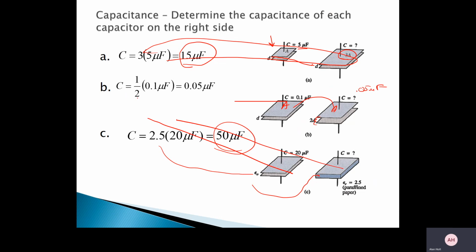But what does happen is those windings can shift for a multitude of reasons. There's blocking between each winding. If one of those blocks shakes out because of vibration or through a fault, or if there's displacement in that winding, then between two windings the distance may increase, but between the other two windings it might decrease.